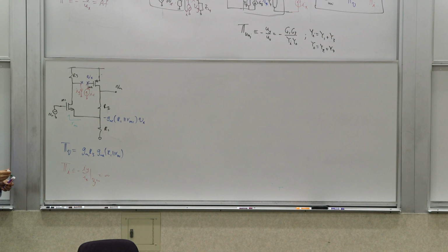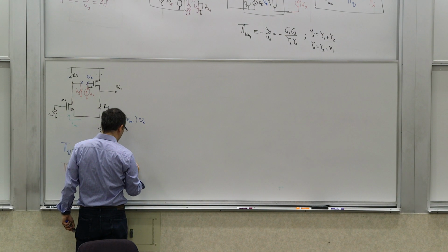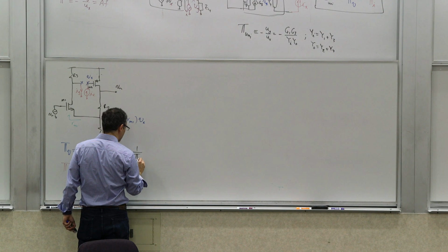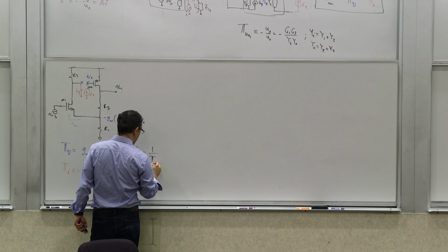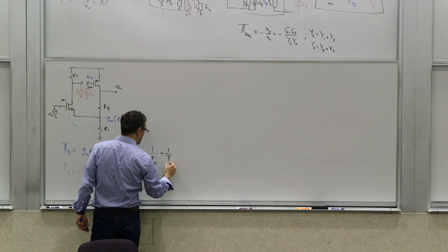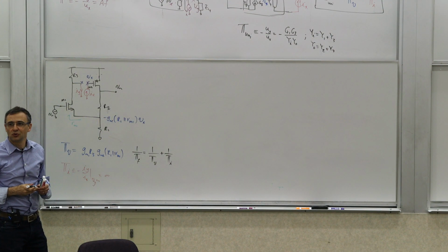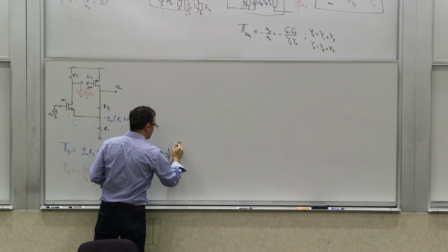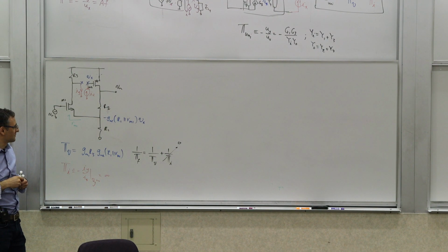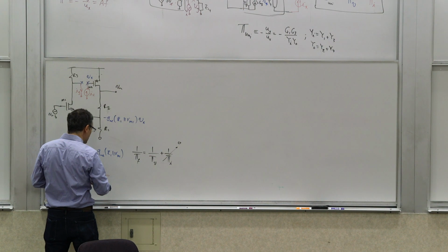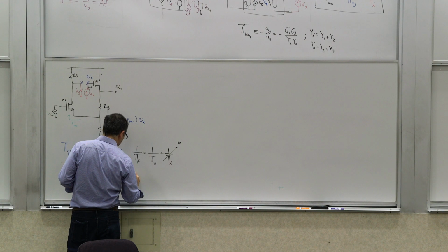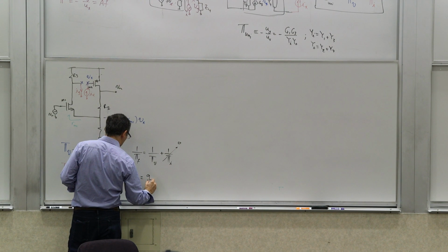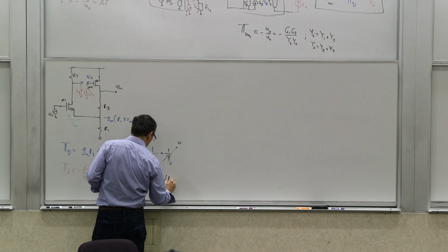That's okay, because the equation we have says 1 over T total, or forward, is 1 over the voltage loop gain plus 1 over the current loop gain. So this one goes to 0. And therefore, in this case, our loop gain is the voltage loop gain that we calculated, which is whatever, Gm1, Gm3, R3, R1 parallel Rm.